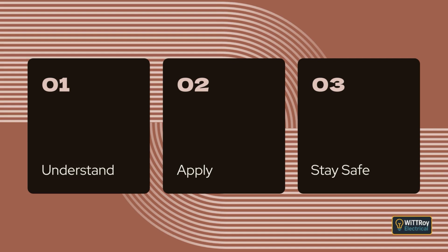Clause 3.3.2.6 Impact. This clause explains that wiring systems must be chosen and installed so the risk of mechanical impact is as low as possible. The wiring must be able to cope with whatever knocks or strikes it might face. The protection can come from the strength of the wiring itself, from where it is located, or from adding mechanical protection such as covers or enclosures.